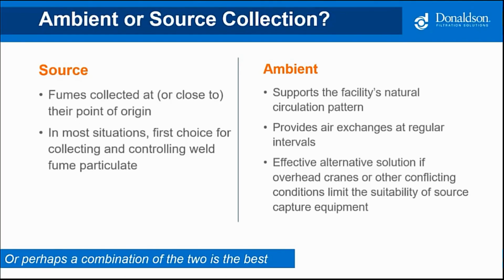In most situations, the first choice is going to be source capture, and we're going to see why here in a bit. Source capture typically requires a smaller hood, smaller air volume, and lower static resistance. Those two numbers, the higher they go, the larger the capital expense the customer will have to make.